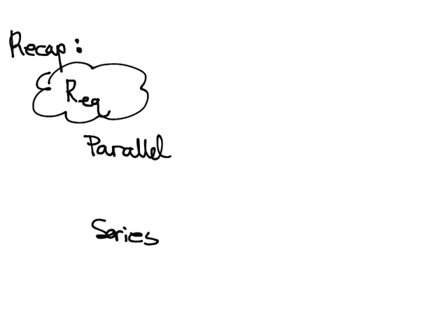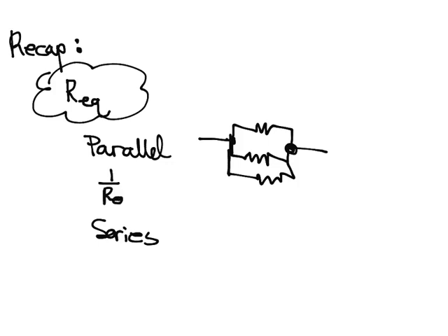Just as a quick recap, we discussed this in class, but if two or more circuit elements are in parallel, it could be 17, and by in parallel we mean that they're connected at both ends. It doesn't matter what else they're connected to. So these 3 that I'm drawing right here are connected at both ends. Then the way to find equivalent resistance is that 1 over Req equals 1 over R1 plus 1 over R2 plus 1 over R3 plus ... however many resistors you have.